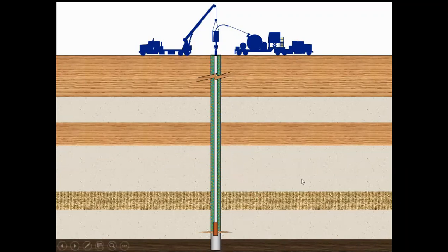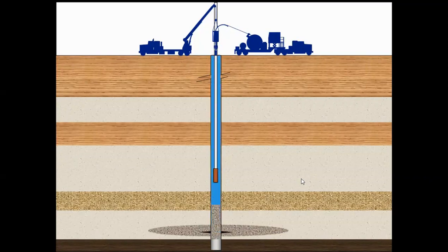What's the next step? So this is the clean out that you have done. Now there is no sand and your perforation is there. So now you have accessed the reservoir. Now you'll pull your coil tubing unit to a certain depth. You will not completely pull it out of hole. We do not do it because we have to save some time, and time is money in the oil field. So we will only pick up your coil tubing up to a certain depth. Then we'll start pumping our hydraulic fracturing operation.